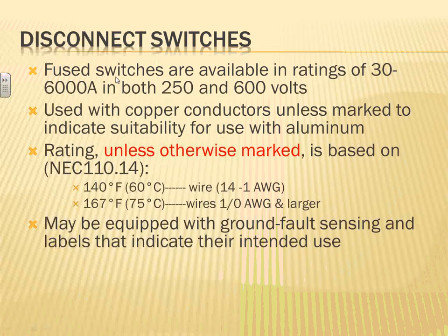A couple of things, guys, about fuses. I don't know if you use a lot of fuses and disconnects versus circuit breakers. At least in my experience as an engineer, we like the circuit breakers because we can parallel them and we can use them a lot. Though when you talk to people who work in the field, fuses have a lot of good advantages over circuit breakers when it comes to protecting electronic equipment.